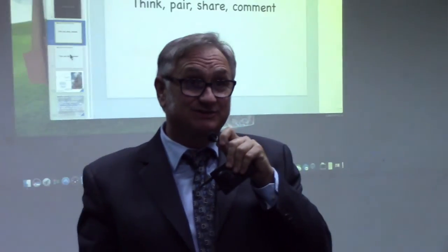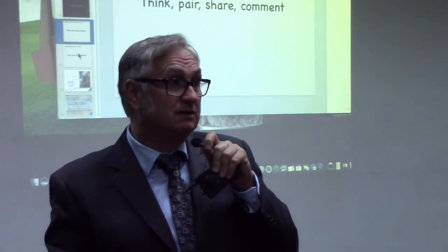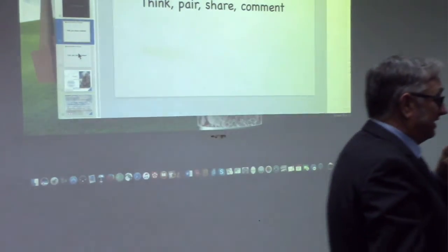But it certainly is true that if you call up a company today to buy an absorber for your campus power plant, they will sell you monoethanolamine in water, because that technology is already proven. Monoethanolamine, why don't we use it? Is that what you said? Yeah, amines in general, the problem is they slip. That is to say, in the course of operating this unit, some of them vaporize and leave into the air, and they're typically not friendly to the environment. They're also expensive.